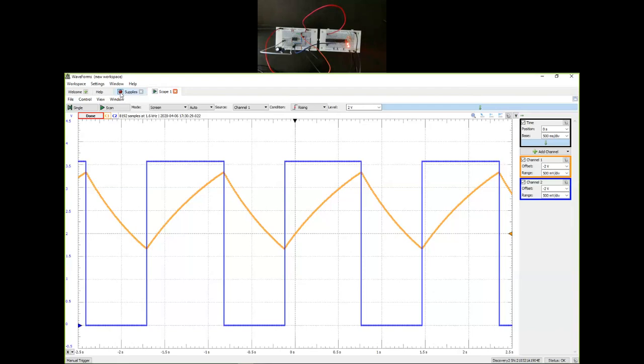Okay, so my counter is now counting, and let's zoom in to take a quick look. Alright, so I'm using the circuit on the left, which is a 555 timer that generates a square wave of time period 1 second, now as the triggering clock for the counter chip. Still we are inverting the clock first and then using that to get the clock input of the 4-bit counter. So it's still doing the counting, but now it's being triggered by a device that we made instead of the analog discovery waveform.